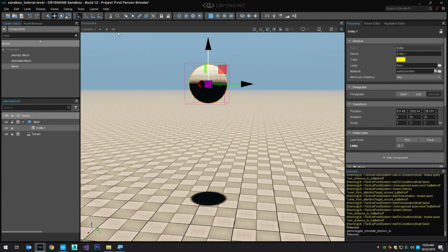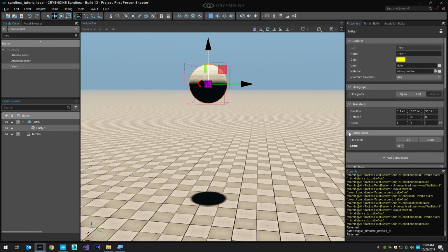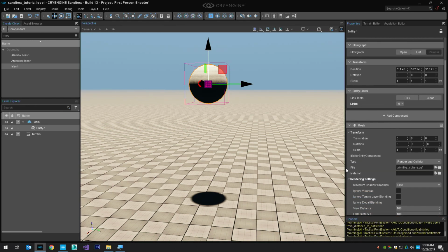So you can turn off your physics. Make sure that this button is back to play, right? This little button. And we're going to click on Add Component again. And this time we're going to go to the physics group and we're going to add what's called a rigid body. By the way, you'll notice a search bar at the top of Add Component. As you start to get familiar with the components, it's much faster just to type the name, unless you really love the mouse.